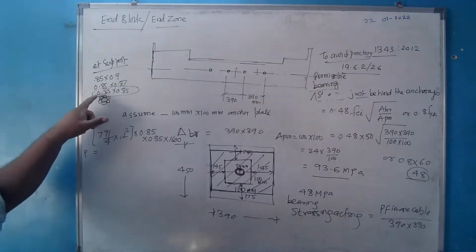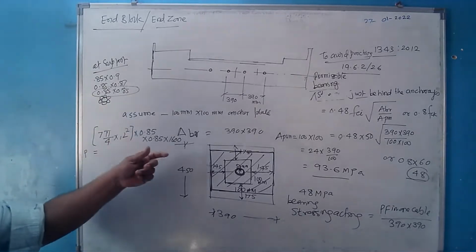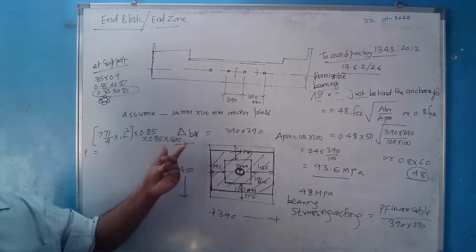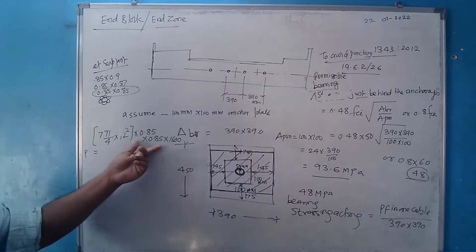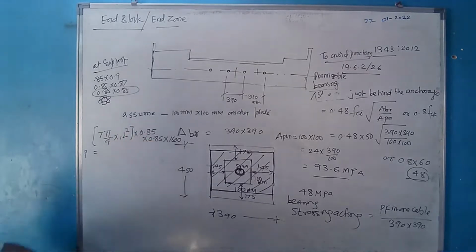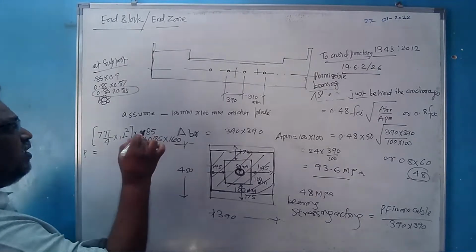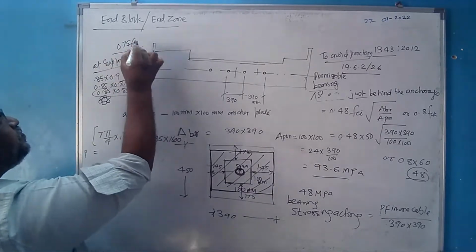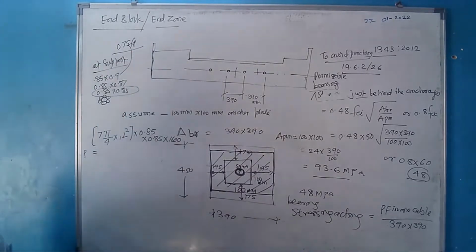There were 7 wires of 12 mm diameter, and the characteristic tensile strength of steel, or the ultimate tensile strength of steel, was 1600. So the permissible stresses are considered as 0.85, or perhaps 0.75 times of FP. There was one clause, it comes from here.